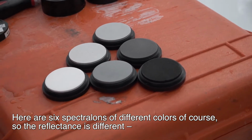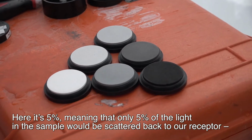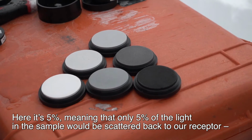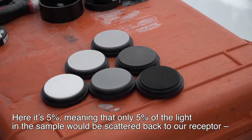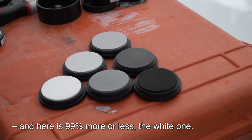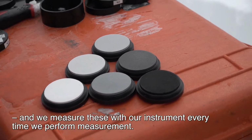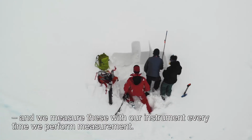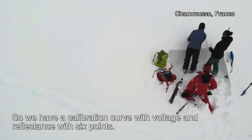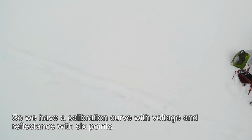So the reflectance is different. Here is 5%, meaning that only 5% of the light hitting this sample will be scattered back to our receptor, and here is 99% more or less, the white one. The reflectance is very well known, and every time we perform a measurement, we measure the voltage directly with our instrument. So we have a calibration curve with voltage and reflectance with 6 points.